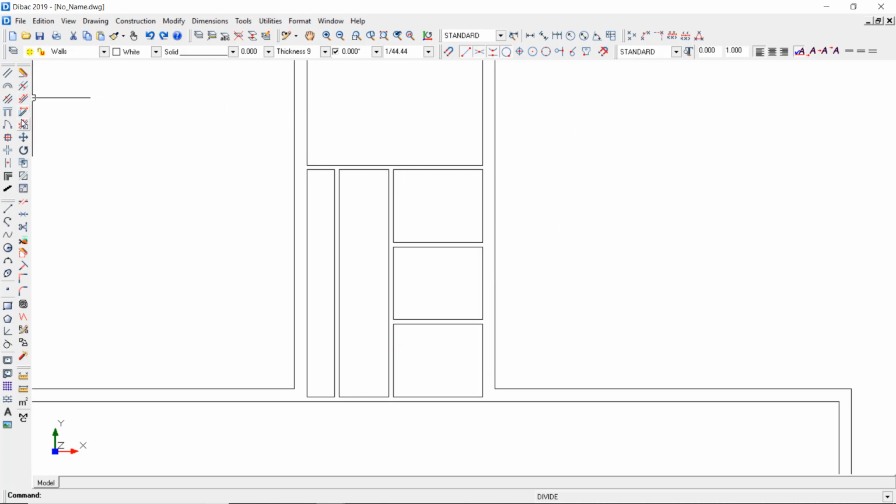Okay, so let's move with another tool. I'm going to use the Lengthen Shorten function to extend an existing wall or line. Just click in the wall, and then you can either type a distance or click in the side of another wall to connect them. Now use the intersection function and click on any of the sides of this wall to fix all the intersections with the partitions.